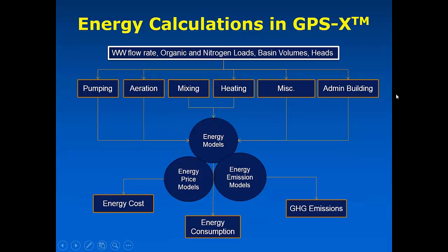So anyway, all of these things are taken into account: the pumping, the aeration energy, the mixing, and the heating, and so on. These things are taken into these energy models, and they're calculated on a unit process by unit process basis, and they're dynamic in the sense that they continuously evaluate the instantaneous amount of pumping going on at any point in time, and calculate the instantaneous energy required to make that happen.